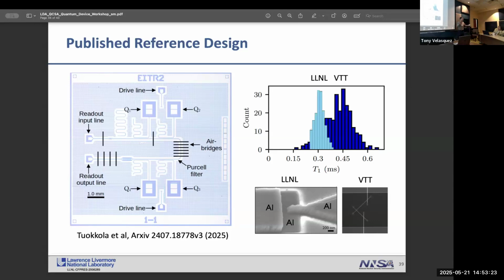I wish we had really nice microwave models to understand how these design choices really impact circuits. It doesn't exist. So your theory is that there's a different surface participation ratio when you read the junction like this? There are kind of different distributions of TLS, in a sense. It's a different way of looking at it, but there are instabilities in all these aluminum surfaces.